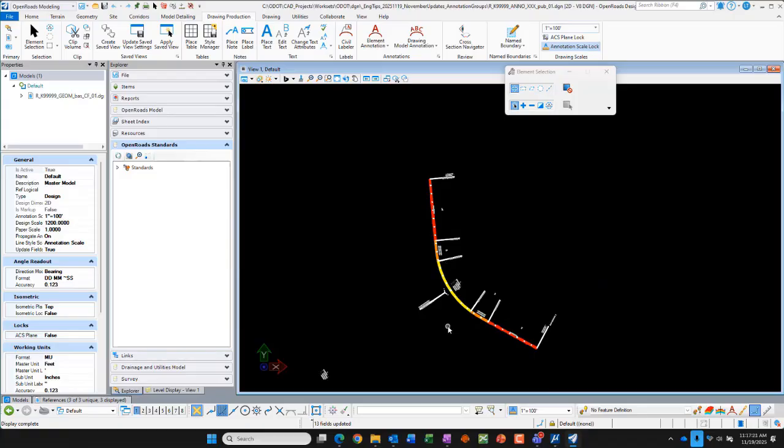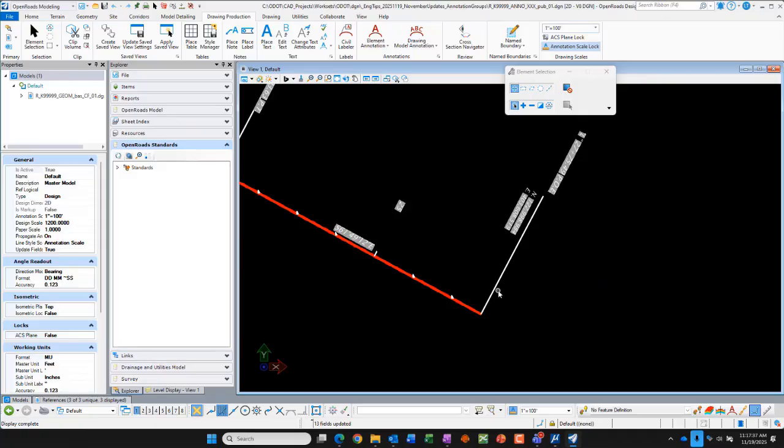So any questions about how that works? Things will stay put now when you move them. Yeah. The text stays put. What about the leaders? No, leaders aren't text. This only works on text, and the leaders aren't text. And you'll notice I didn't bother. If I wanted to extend that, I'd probably just draw a new one and draw it longer.